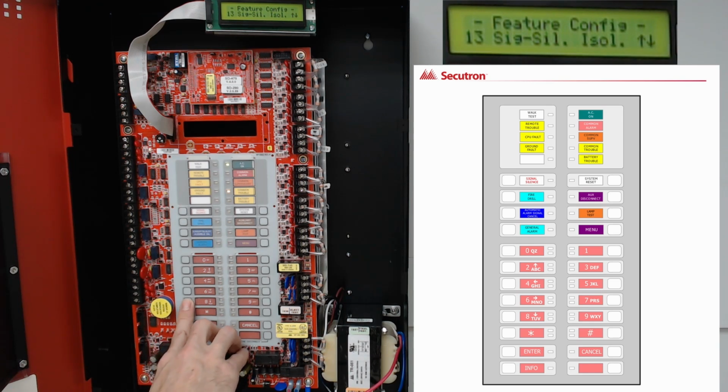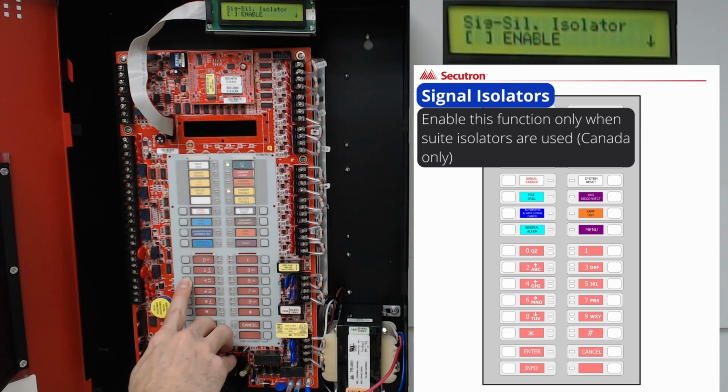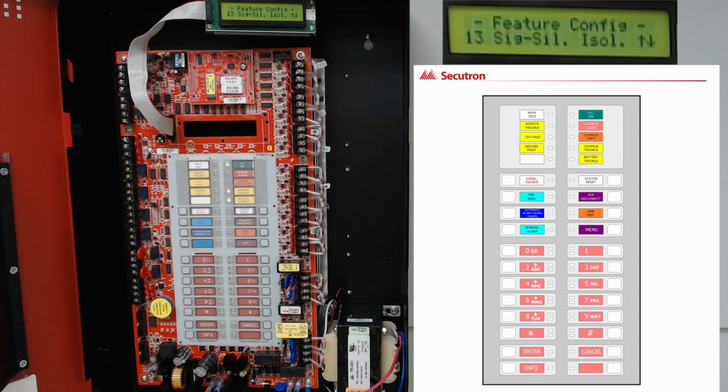The next option under Feature Config is Signal Isolators. By pressing Enter, we get to see the options for the signal isolators. By default, it has already been disabled. If we want to enable it, we'll simply hit the up cursor and then the left or right cursor to apply the X to enable. Now all we have to do is press Enter, and we can again then press Cancel to exit out to the previous menu screen.